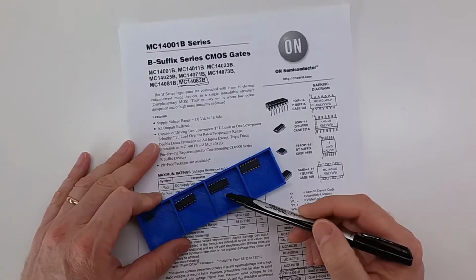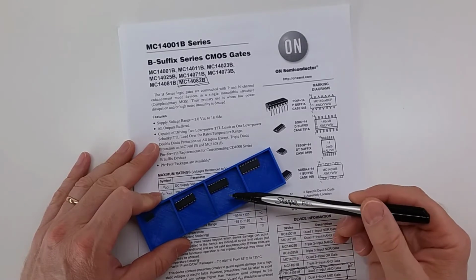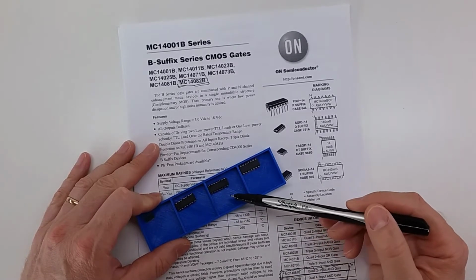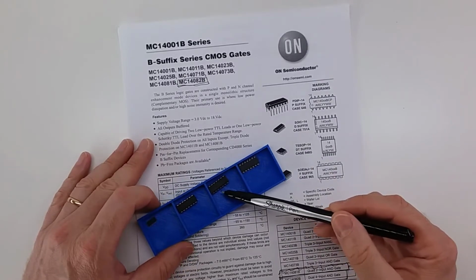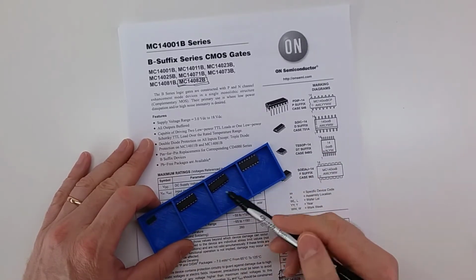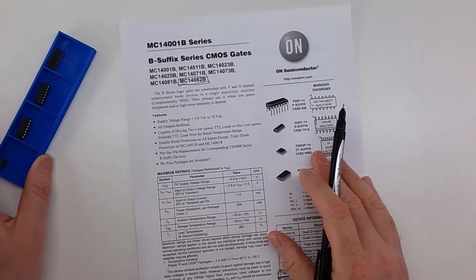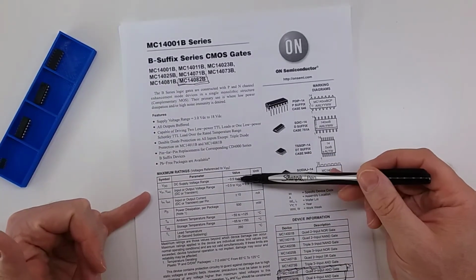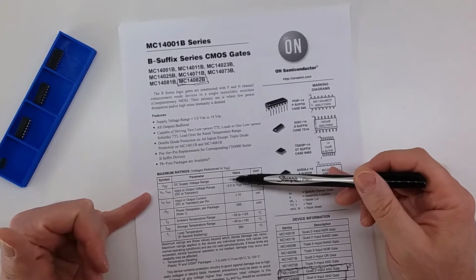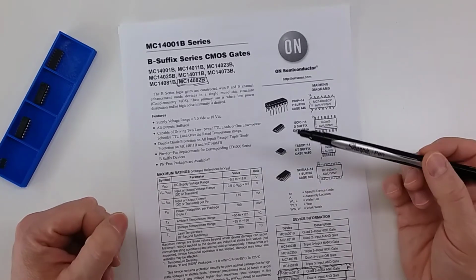This is that third one, and this is going to be that dual quad input. So what that means is there's 4 inputs instead of 2, but then subsequently there's only 2 within the package since it's still the same exact size. So this is the data sheet for that. This one also has a large voltage range between minus 0.5 volts and 18 volts.